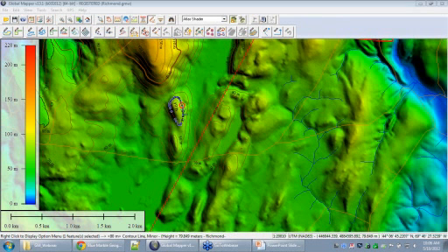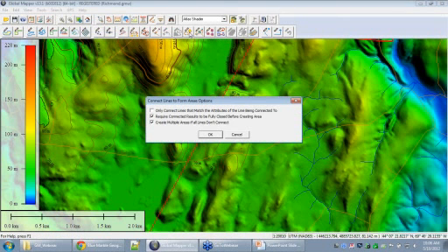Okay, yeah, you have to create it from an area feature, not a line feature. Oh, I'm sorry, that's right. What I can do real quick with that digitizer, I've already got it selected. Up on the digitizer panel, there's a little tool to create an area feature from a line feature. So that's what we need to do first. Thanks for the tip there, Mike.